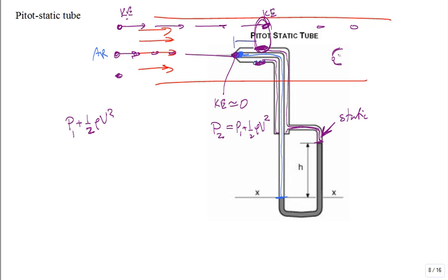So what you do also is you come back a little ways, and you don't put the slots for picking up the static pressure real close to the tip. You put it back a little ways, so that if there is a little flow separation, it gets reattached, such that these tubes are measuring the static pressure a little ways away. It's not influenced by some two-dimensional, three-dimensional flow right in the near vicinity of that curvature.